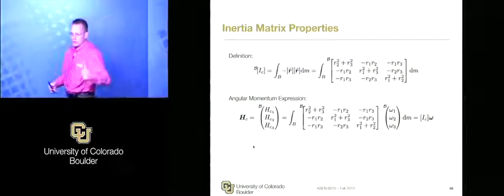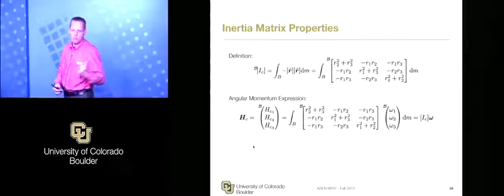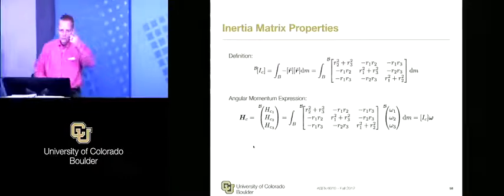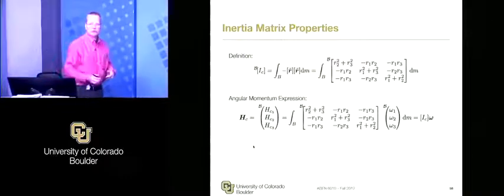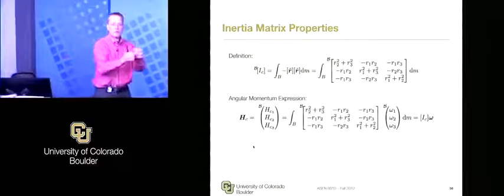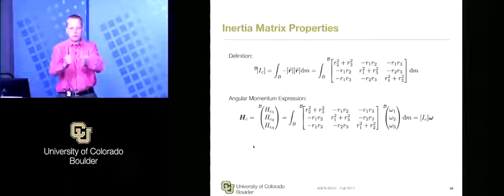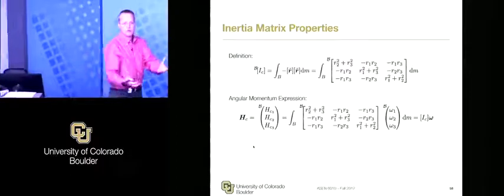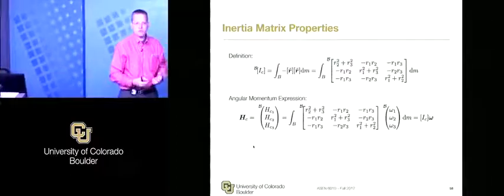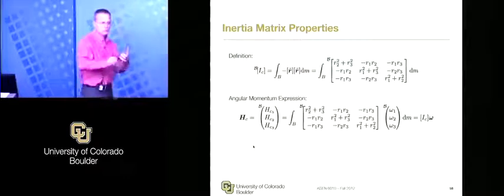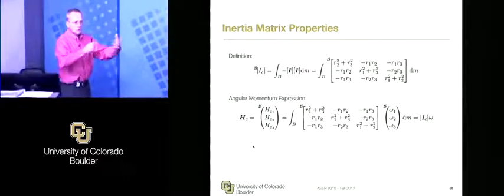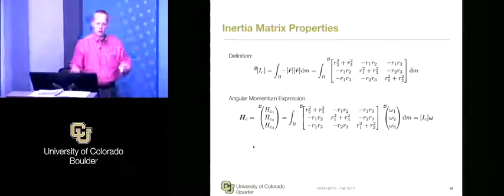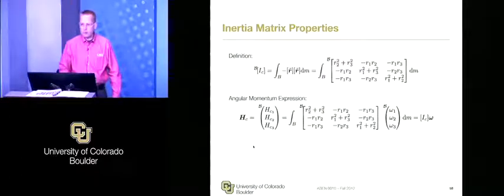The sum square of these components has to give you the same thing. And we used that to make what kinds of plots? For torque-free motion? Polhode plots, exactly. H1 squared plus H2 squared plus H3 squared has to give you a constant, and that turns into the sphere equation in momentum coordinates, right? And the energy expression in terms of momentum coordinates was an ellipsoid. So the resulting omega history came out of the intersection between an ellipsoid and a sphere, right? That stuff. It's all coming back, kind of.